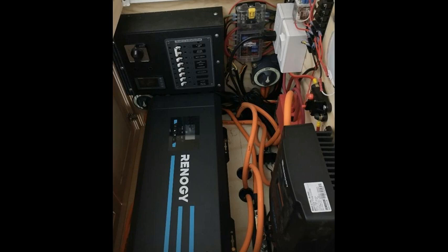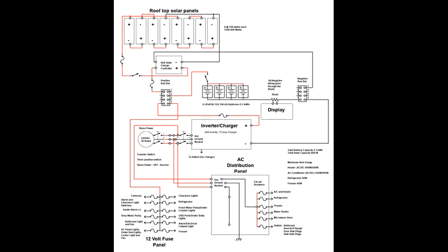It is recommended that the breaker box be close to the inverter. The wiring from the inverter to the breaker box must be able to handle the total system power requirement. As mentioned in previous videos, you need to create a schematic diagram and any necessary notes. Be systematic and methodical in your design. For each circuit, start from the breaker box, move to the switch, and onto the load.